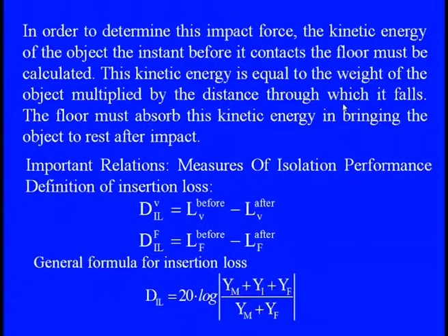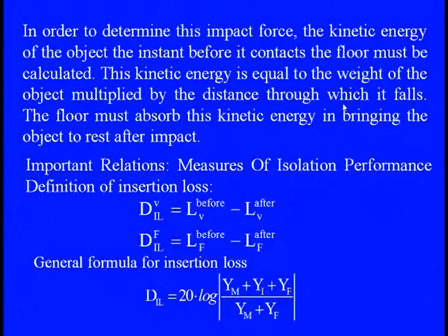So the level of velocity before and after gives the insertion loss, or even the forces can be applied to measure the isolation performance with insertion losses. As a generalized form, the insertion loss DL equals 20 log of (Ym plus Yi plus Yf) divided by (Ym plus Yf), depending on the distance and the force applied.